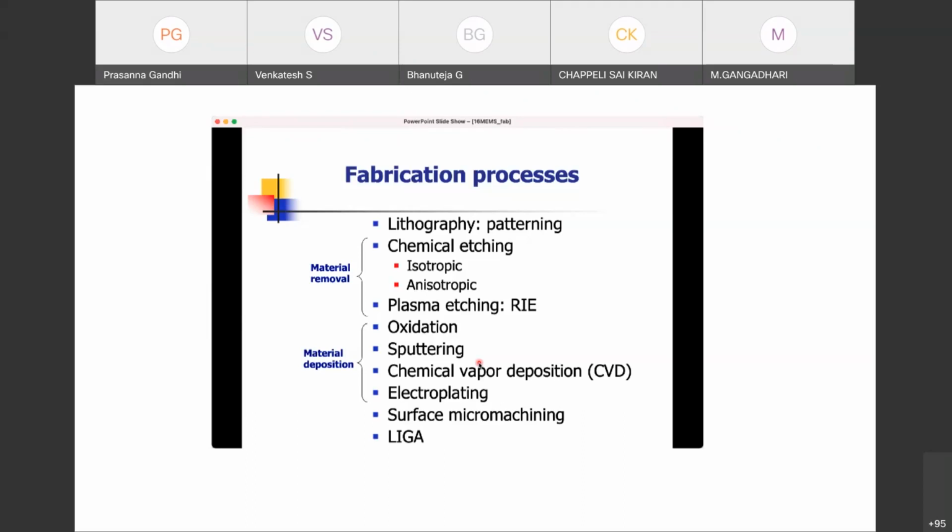So this is a base philosophy that you should understand very strongly to really understand how the MEMS processes work. Our normal thinking in the mechanical domain, of doing machining and creating some component out of it, that kind of philosophy doesn't work here, because all these material removal processes are predominantly surface processes. And this material deposition also is a surface process.